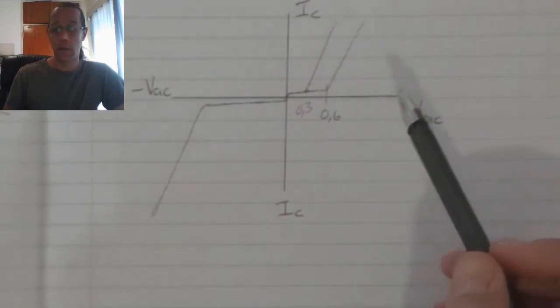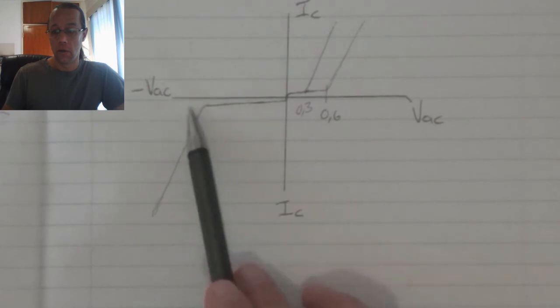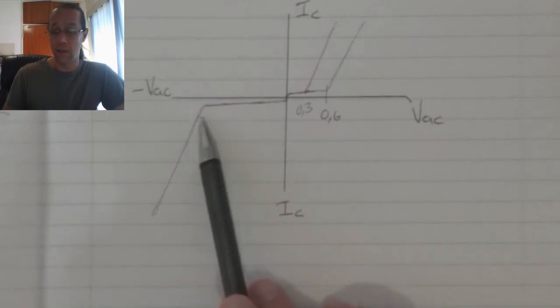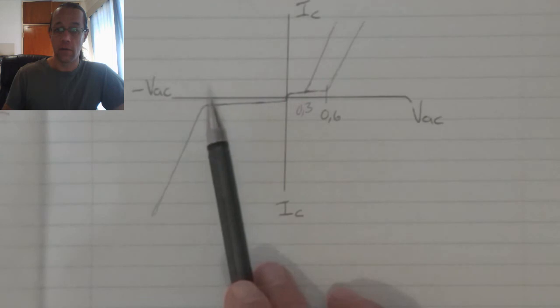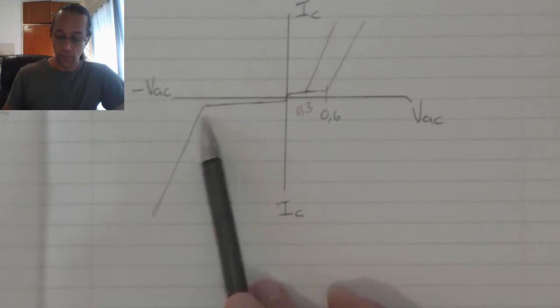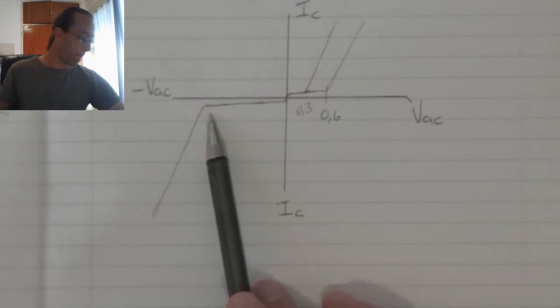Now, for a typical diode, this happens above 600 volts. Now we know that current flow is directly proportional to the voltage. So if I've got 600 volts DC connected onto a diode, the amount of current that's going to flow is going to be so much that the diode is going to burn out.